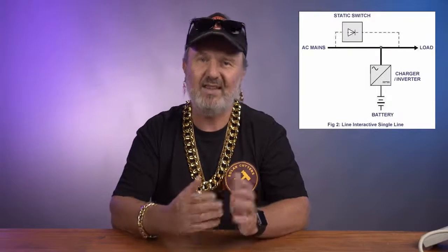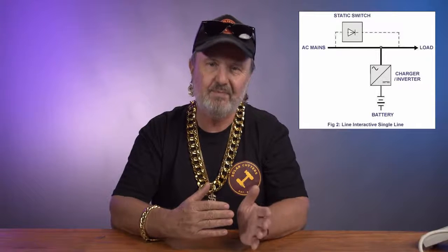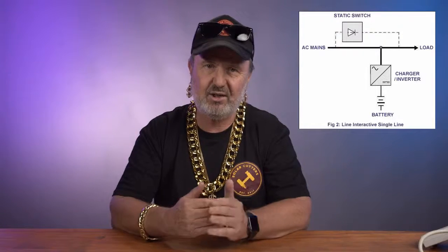What's an interactive inverter? It's one that can parallel its own inverter function with another source, such as a generator. That means it's running in synchronization with another source. It also means that energy can flow in multiple directions. It can flow towards the load, and it can flow towards the generator, especially under disconnection.